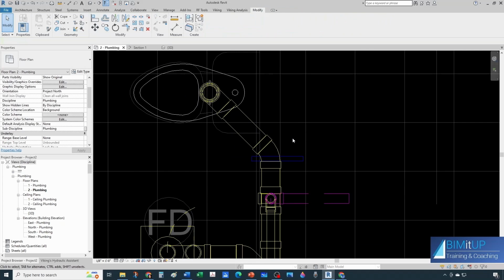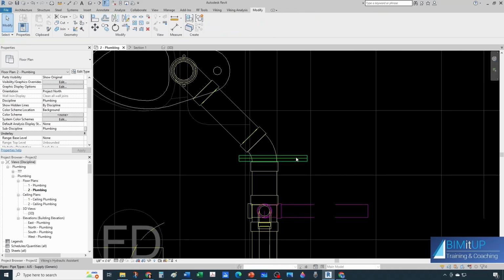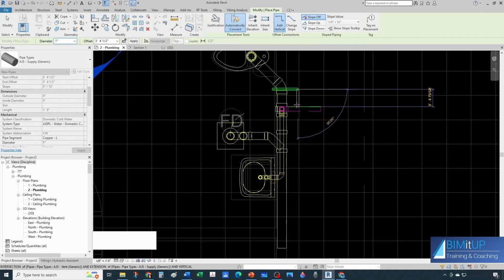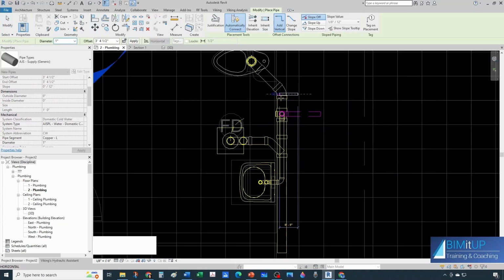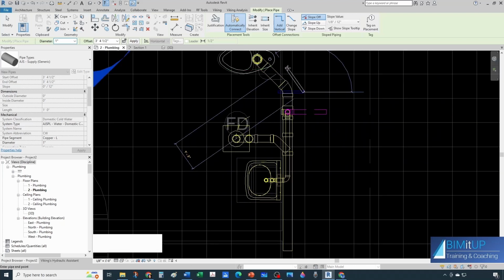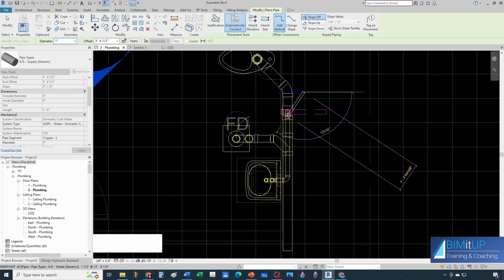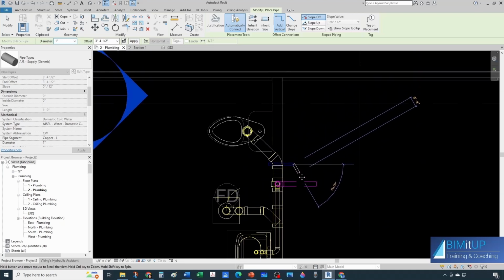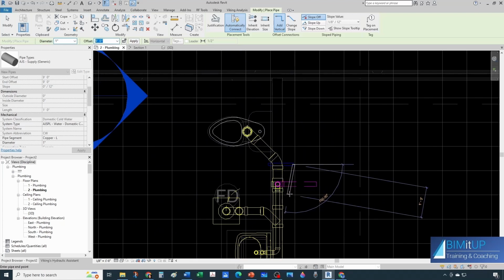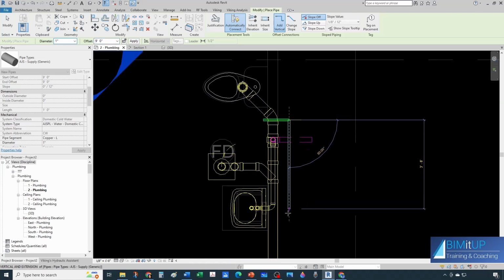Now I'm going a little bit past the wall and I'm going to align that later, but it's gonna be easier for me to do it from the outside. So we have two options here. Either we could navigate within the wall and then feed the water closet, feed the lavatory, and then go up to the ceiling space and keep going. But in this case, this wall is pretty narrow and we have our vent stack here, so it can be a little bit congested. So I think I'm just gonna go up to the ceiling space. So let's take this to 9 feet and then come this way.